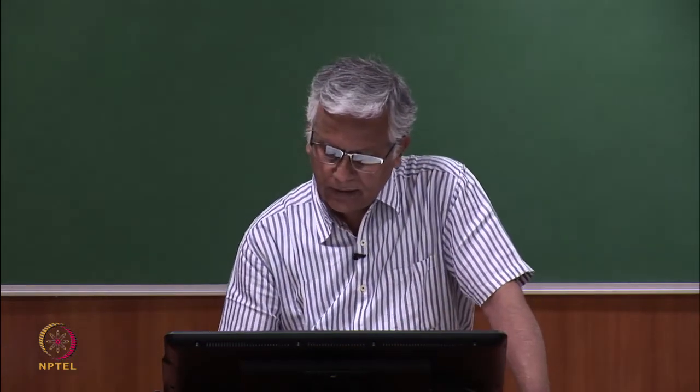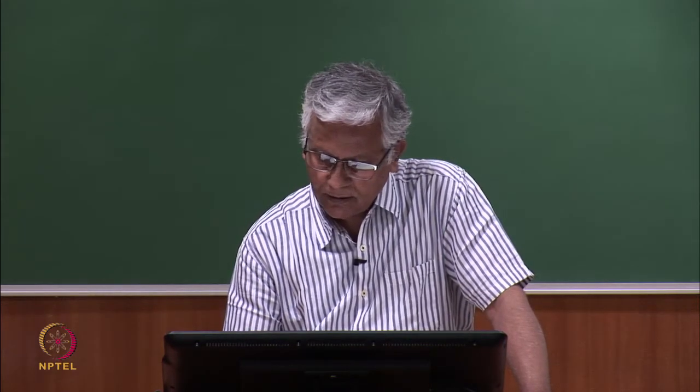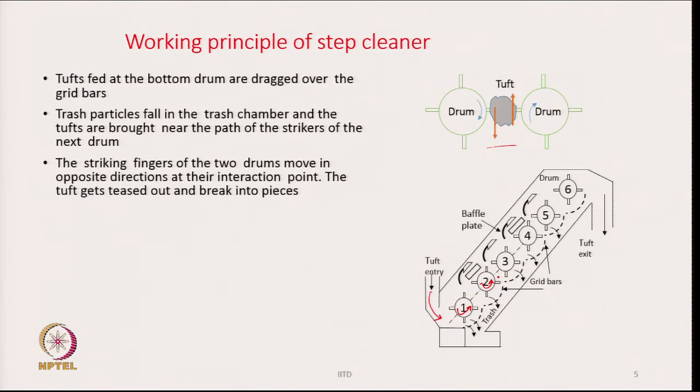That is what is going to happen here. So, all these drums are rotating, and there is a possibility of a mild opening action in between by the fingers on the tuft, a little bit, but not much, and the tufts will be dragged over the grid bars.